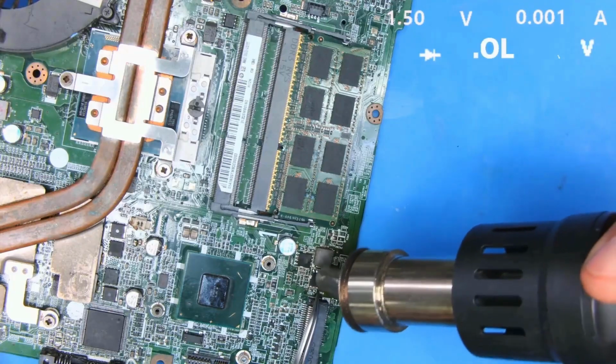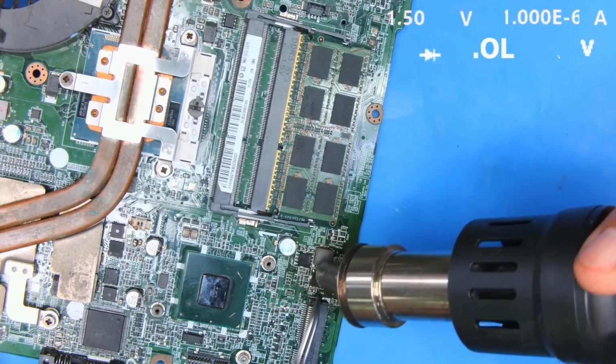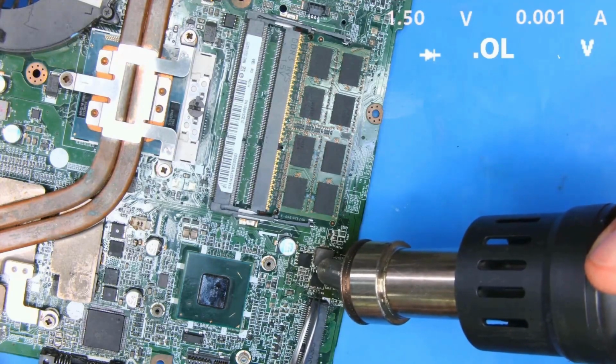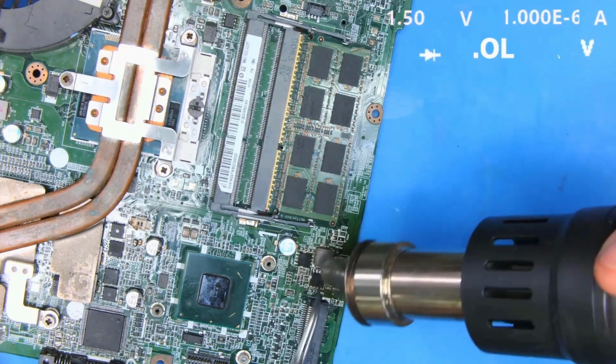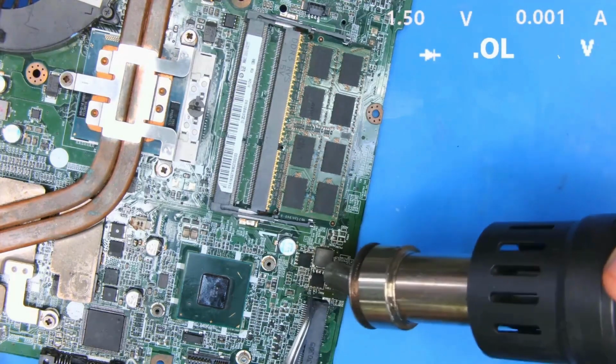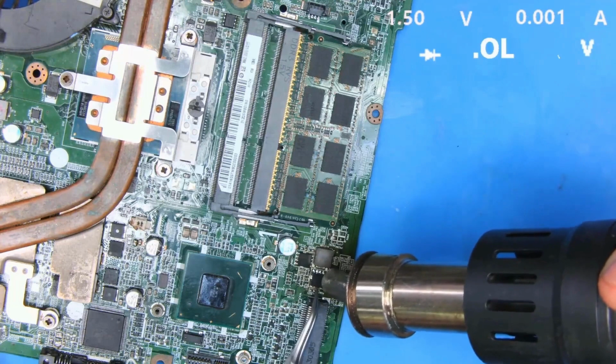Some people like to make it look perfect right away, but if you use the hot air for too long, it gets really hot. Once it gets really hot, the board can potentially swell. Try to stop and then carefully adjust it again if absolutely needed. Squeeze the tweezers firmly together and meticulously adjust left and right until it's perfectly straight.